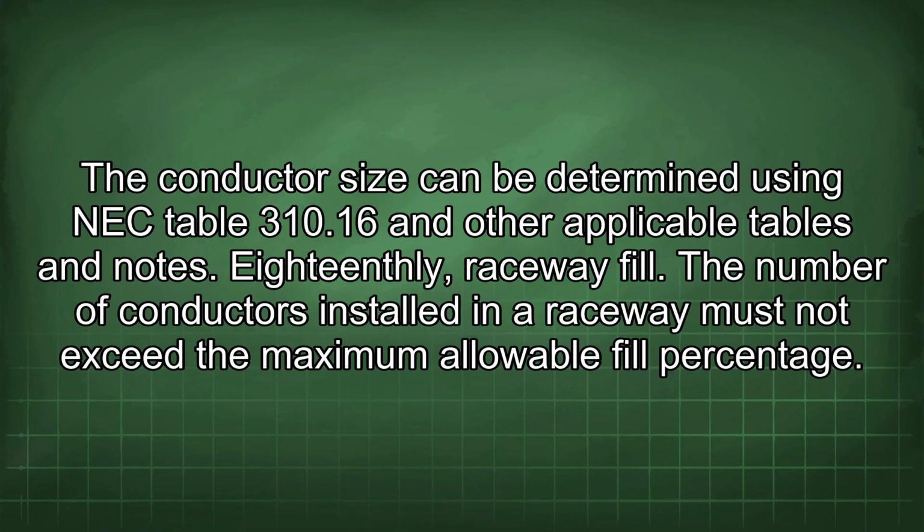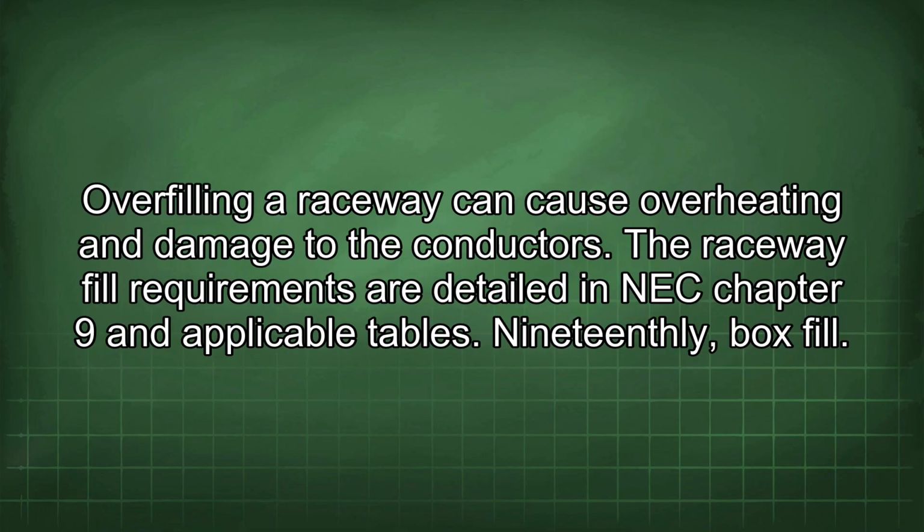18thly, raceway fill. The number of conductors installed in a raceway must not exceed the maximum allowable fill percentage. Overfilling a raceway can cause overheating and damage to the conductors. The raceway fill requirements are detailed in NEC Chapter 9 and applicable tables.